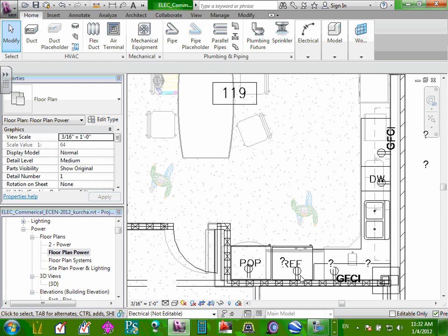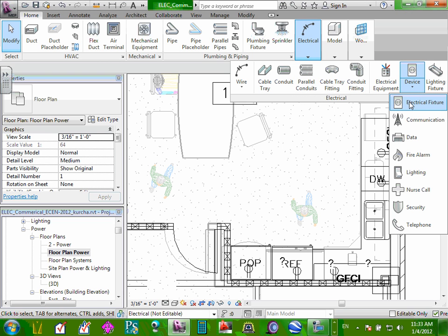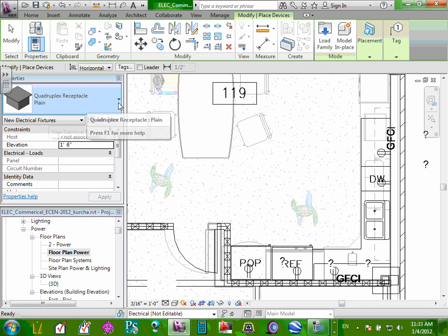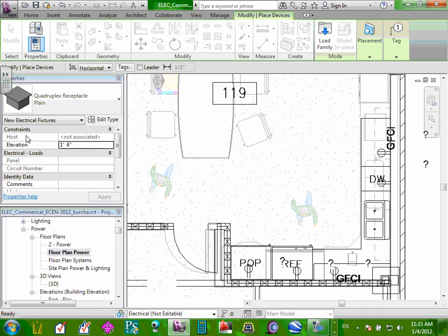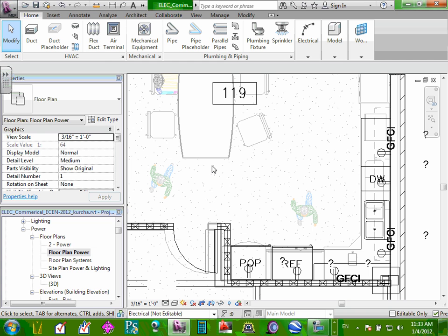This is a countertop for kitchen. So you might have to throw another receptacle right here. I think it's a good idea, but I didn't ask for it though, so you didn't do it. I'm not going to hold you accountable for it. I want to put a GFCI receptacle right in this area on the countertop. Remember, this is not a residential, so the rule 2/4 does not apply to it. You don't have to do that.